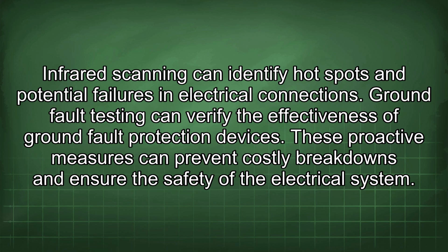Infrared scanning can identify hotspots and potential failures in electrical connections. Ground fault testing can verify the effectiveness of ground fault protection devices. These proactive measures can prevent costly breakdowns and ensure the safety of the electrical system.